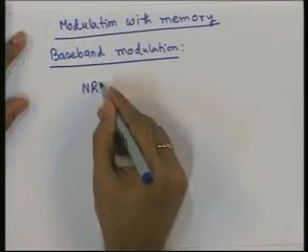But there is another scheme where the transmission of 0 volt is not preferred, but you transmit a negative voltage for 0. That is called non-return to 0 scheme, because you do not return to the 0 voltage, but go to the negative voltage, toggling between plus and minus voltage. That is abbreviated as NRZ.